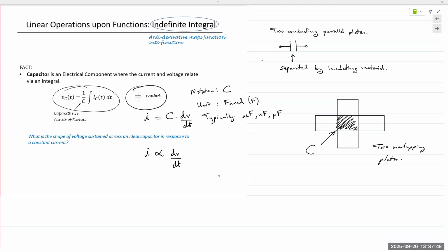The capacitor has stored the energy, and there is no pathway for the capacitor to release the energy yet. If you send energy to the capacitor, the capacitor stores the energy. If you remove any connection to that capacitor, meaning there is no pathway for the energy to discharge, then nothing will happen. It will keep that energy stored. When the shutter button is pressed, a pathway opens, a signal is sent, and the capacitor releases all that energy at once to the light bulb, and then we see a flash. Hence the name of the device is a flash. So to answer your question, it depends on the application and how long we want to keep it.